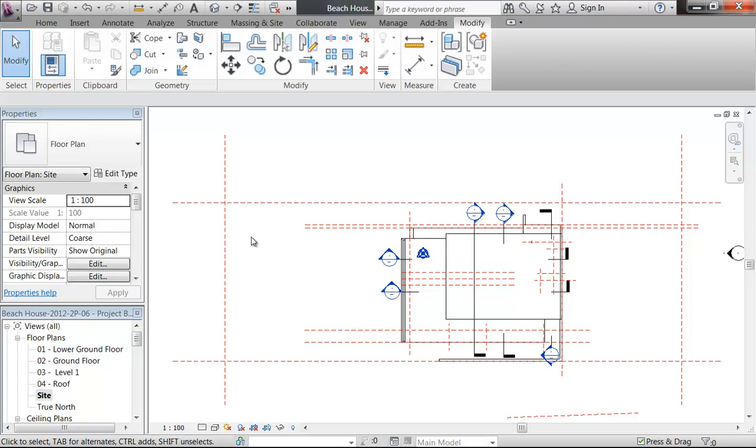Now, getting the heights here is going to be a little bit tricky because you're not given those anywhere on these drawings. Normally you would be. If you're doing a real project, the first thing you'll be given is a survey with all the heights for the ground. But in this case, we're going to have to use a bit of guesswork.